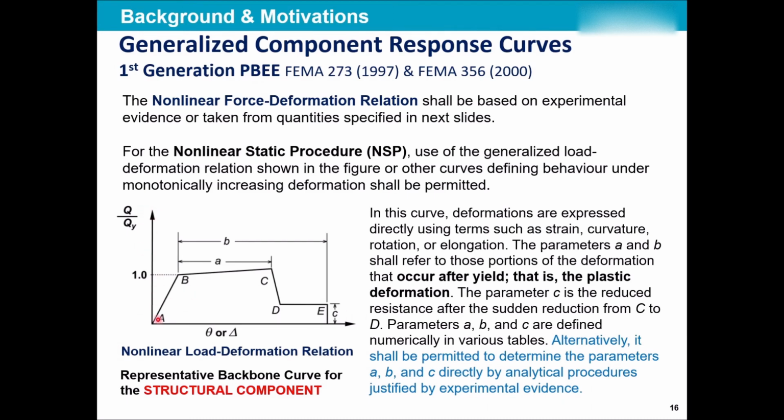What happened is, for each component they managed to give a curve, whether force versus displacement or moment versus rotation. They got monotonic curves which were representing the behavior of that component. By giving values for A and small b, you can always plot these curves. Now, having these curves ready for every single component of your building, which is usually limited to few types of component. Anyhow, not every single column of your building is different. Usually we make all of the columns similar, so the construction will be easier as well.